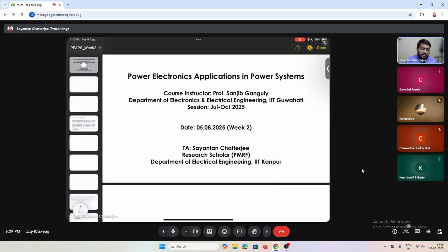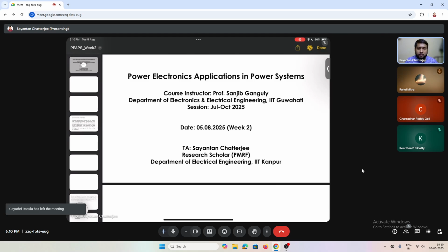In the medium transmission lines, the capacitances are considered, but these are also lumped, according to the pi models, T models, and so on. On the other side, in the long transmission line, the capacitance effect is also considered, and it operates in a distributed fashion, meaning distributed parameters are considered, as we have already seen in detail, and the mathematical derivations have also been discussed pretty well. So, if you have any doubts, you may ask. Otherwise, we will proceed.